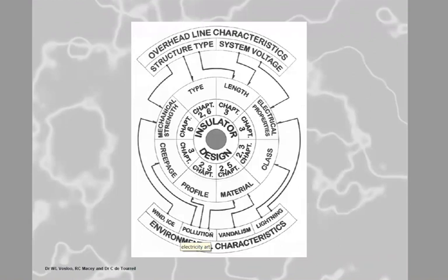Can you do anything about the voltage? No. Can you do anything about the resistance? Yes. Now, what is R? R is equal to rho L over A. Right, cool. Now you see it in your mind: R equals rho L over A. What is L? Length, and that's your creepage distance. Cool. So the higher the creepage, the higher R, the lower I. You got it?